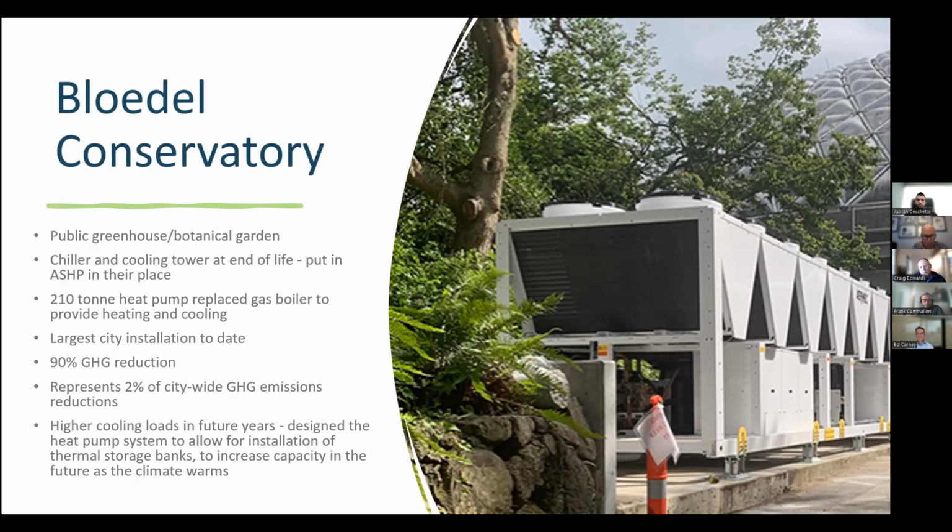So the main challenge that we ran into with this project is we've only got one air source heat pump, so it goes into defrost. The biggest challenge for us in Vancouver is temperatures close to 0 degrees Celsius, slightly above, when it's pouring rain. Then we get a lot of frost buildup on the coils because the coils are cold in the rain. So it's not even the colder temperatures that are the biggest challenge. It's actually the temperatures just right around 0.